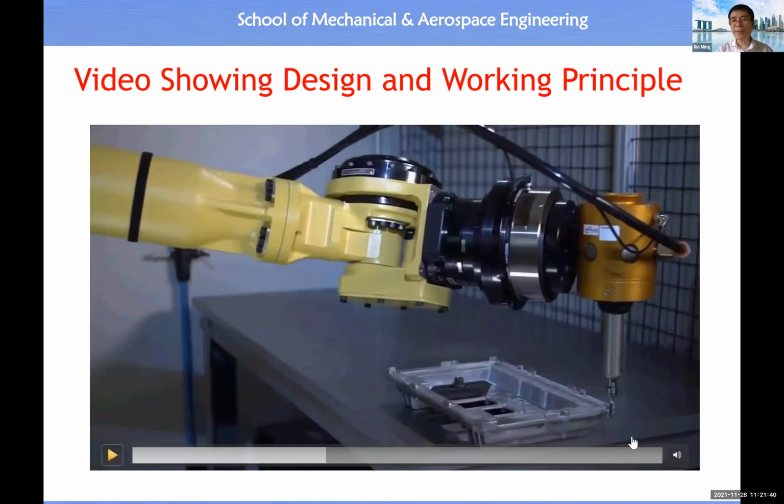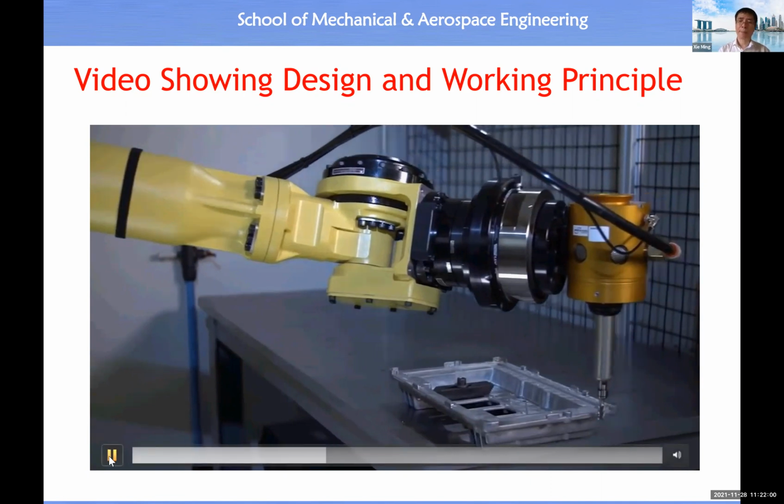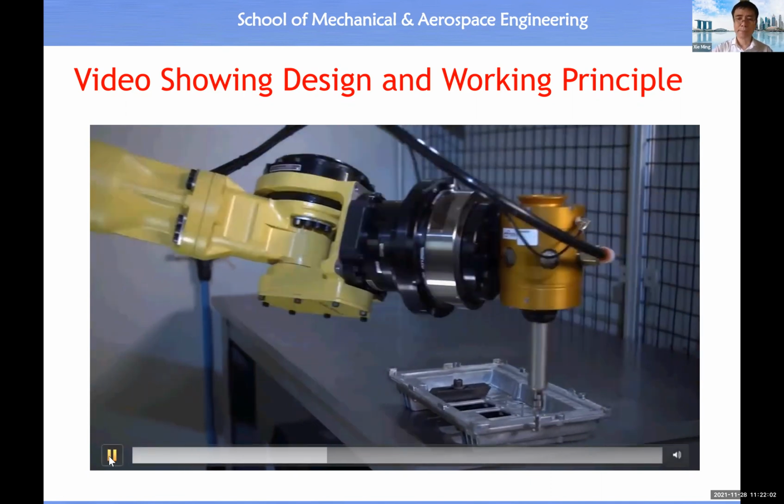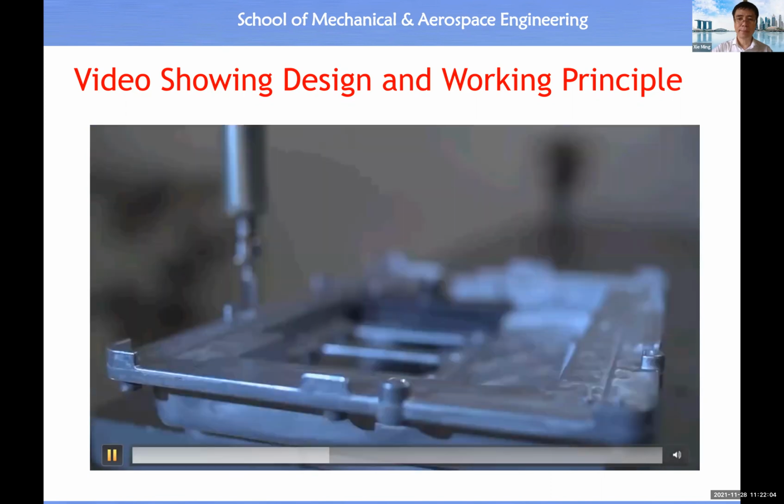Okay, so this is a typical scenario of doing constrained motion because there is an interaction between the robot's tool or robot's hand and the workpiece. Therefore, you must have a force torque sensor to measure what is the actual interaction between the tool and the workpiece. ATI force torque sensors can withstand overloads between 5 and 20 times the rated measurement range.